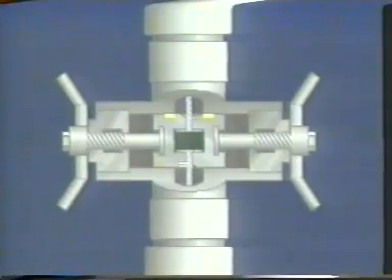The rams also seal in the body of the wire line valve to prevent well pressure from escaping around the ram when the valve is in the closed position. The wire line valve is designed in such a way that when the valve is closed and pressure is released above the rams of the valve, the well pressure trapped below the rams holds them in a closed position. To reopen the valve, pressure must be equalized across the rams.